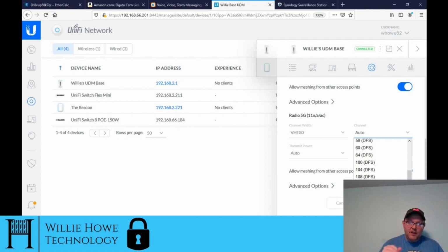But these channels, because that is in the public band, but it is DFS, when somebody who's transmitting radar needs to transmit on those, they get the preference. And so you'll always see, if you're reading release notes from all these different manufacturers, is they are waiting for their devices to get DFS approval and all that stuff. So there's a whole lot of stuff that goes into making sure that you're designing your Wi-Fi